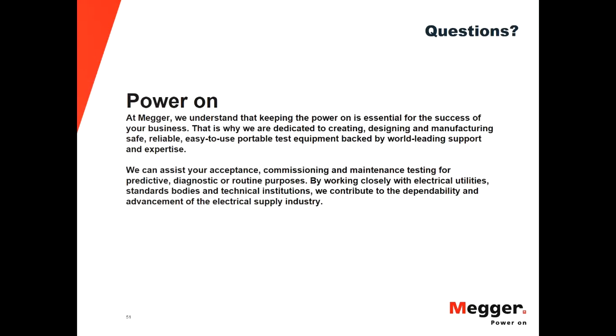The test is considered destructive for a couple of reasons. One is that every time you discharge the battery, depending on how deep you go in the discharge, you are taking a cycle out of the battery. The same way that batteries are specified for a certain life expectancy in years, there's also a spec for the cycles on the battery.